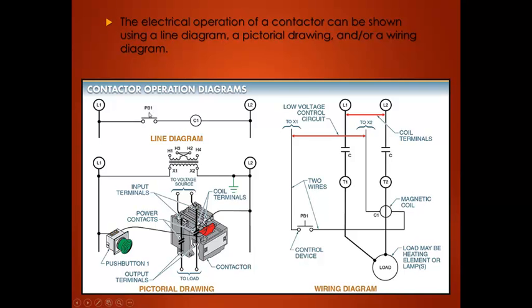So in a line diagram, push the push button, energize this coil. When this coil is energized, it closes these contacts, connecting this power to our load.